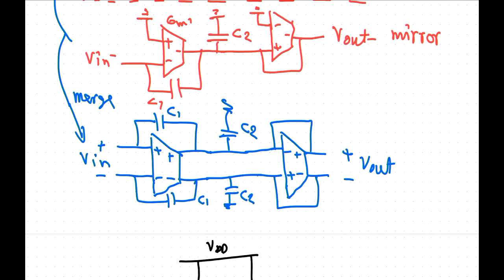So for very high frequencies, the impedance of these capacitors is dominating over the impedance of the transconductance. So the transfer function from here to here is just going to be the capacitor division you have between those two, which is another way to look at it. There must be a zero sitting in there. So the other one was a low pass filter where the gain drops like that, and this will go out and be constant at some point, because at high frequencies we can ignore these ones here. That's just to the output node. So that's a zero sitting in the transfer function.